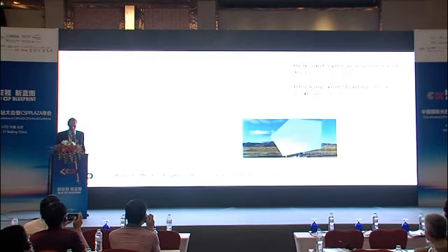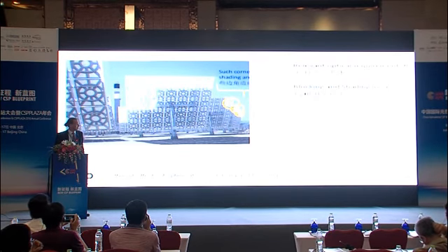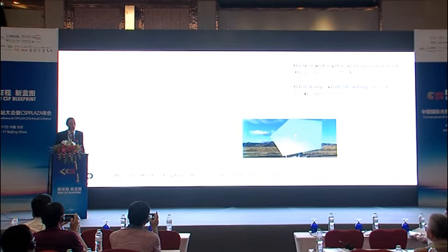Quite important is also the geometry of the heliostat. What you can see on this picture is that mostly the corners shade and block each other. So if you think about cutting off the corners, you come in the end to a round heliostat, and that's actually what Stereo is doing. We try to have a roundish heliostat to be able to have less shading and blocking and to push the heliostat field closer together.